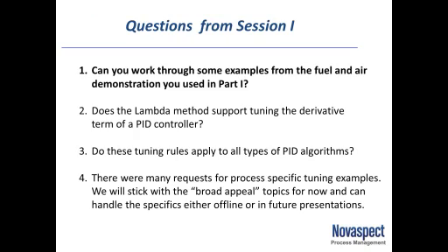The second question I got was, does the Lambda method support tuning the derivative term of a PID controller? Yes, it can. There is a place for derivative control, and there are variants of the Lambda method that can accommodate those tasks. However, the simpler proportional integral only models provide very good results for the vast majority of real-world loops. In the interest of providing the biggest benefit to the broadest audience, I'm still going to stick to the proportional integral only today. Still no derivative.